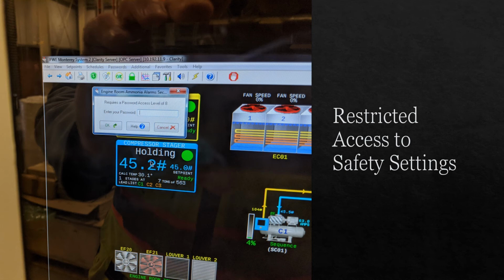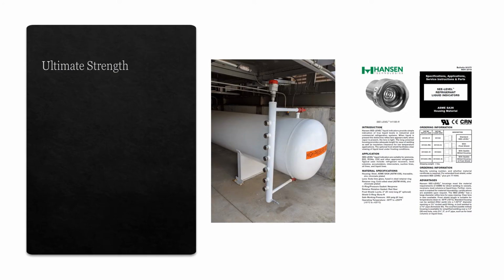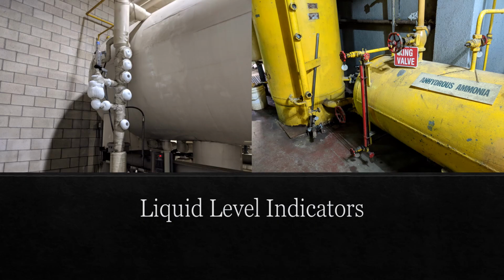Refrigeration system safety settings must be limited to authorized personnel only. This is often achieved through password protection on a PLC HMI. Any instruments and visual level indicators must have a maximum allowable working pressure equal to or greater than the system in which they are installed.